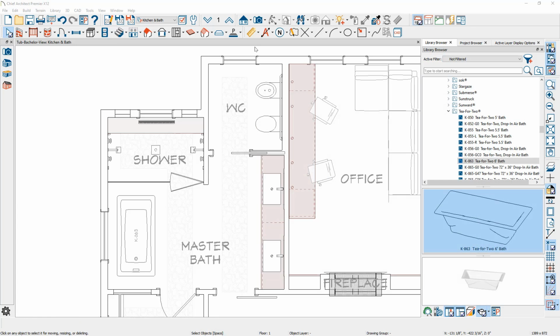When creating a bathtub platform in Chief Architect, there are a few different tools you could use to accomplish the job. One of them is our Polyline Solid tool. It's a very flexible tool that creates solids. You can put holes in them to cut out the bathtub. I recommend you use the Custom Countertop tool. It will allow you to shape it and put edge profiles on different segments and create more flexibility when you create your bathtub platform. And I'm going to use this tool to create the tub platform.